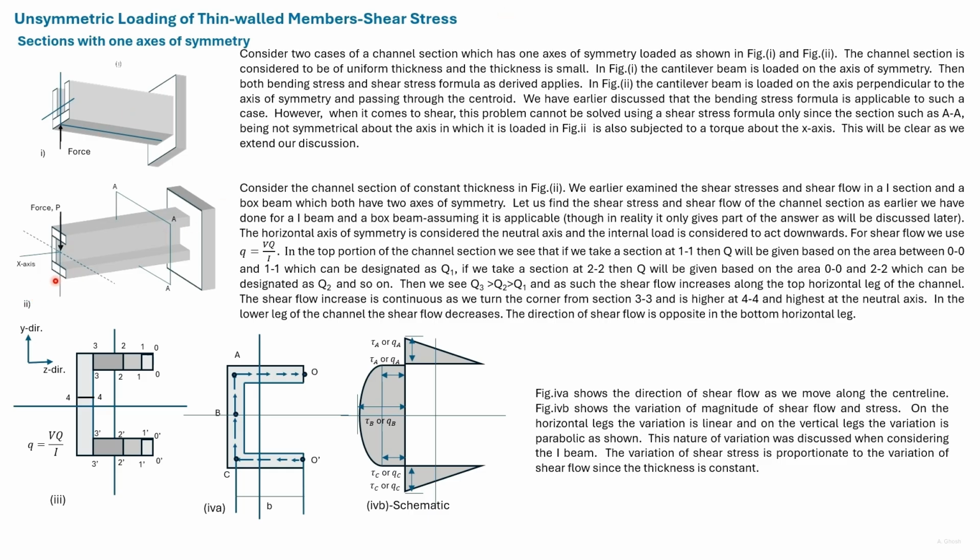In figure 2, this axis is perpendicular to the axis of symmetry and passes through the centroid. If a load is applied along this axis, then determining the shear stresses in the section is more involved, as we shall see. Let us start our investigation by assuming that the shear stress formula is applicable. We can then find the shear stress and the shear flow in the channel section.